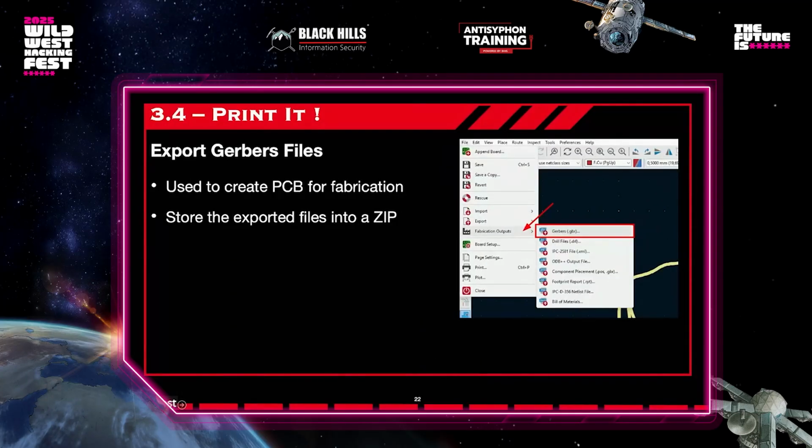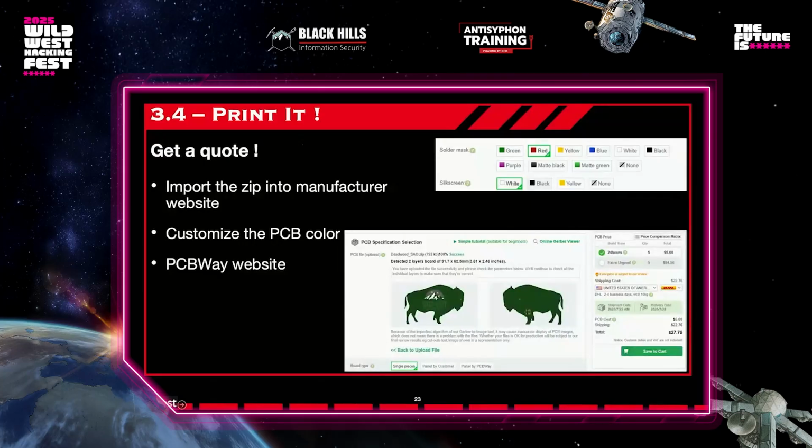Once it's done, you can just export the Gerber files for fabrication. So just go into the files and export Gerbers and store those in an archive like a zip file. And once it's done, you can just import that zip file to any factory. Mostly they are located in China. This is an example with PCBWay, so I just import my zip file. It's going to show me the actual PCB.